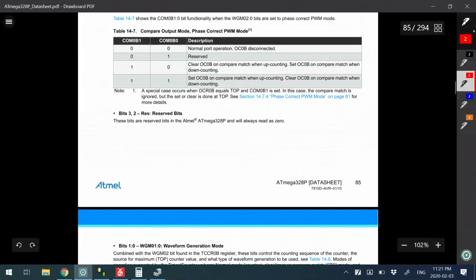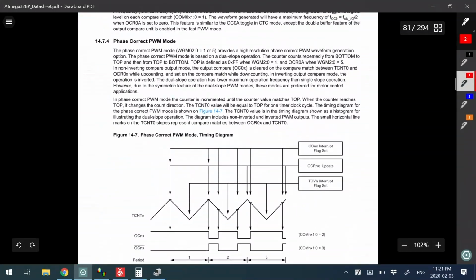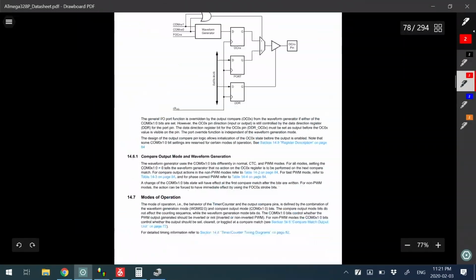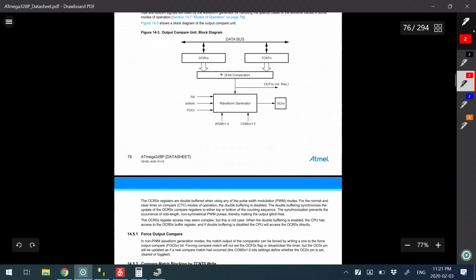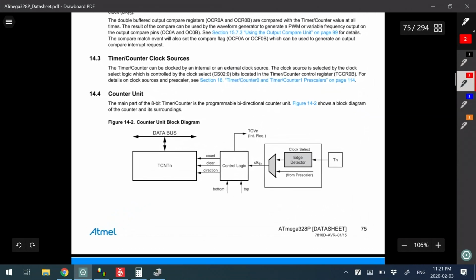What we have is a timer 0 on the microcontroller. Take a look at the microcontroller datasheet, and it basically explains how there's a timer module. Here's what we care about, which is this little count, TCNT0, and it just counts up. It keeps going up from 0 to 255. It's an 8-bit counter, so that's the maximum value it can have. And then by default, it just wraps around back to 0.